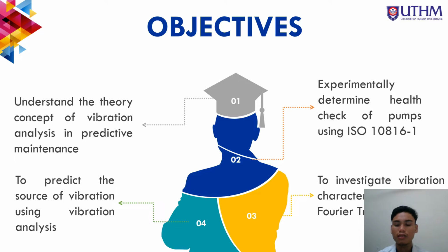For the objectives of this research, the first is to understand the theory and concept of vibration analysis in predictive maintenance. The wave terminology and vibration terminology can be understood from the research. The second is to experimentally determine the health check of pumps using ISO 10816-1. We can determine whether the health is good, satisfactory, unsatisfactory, or unacceptable when the pump is running.